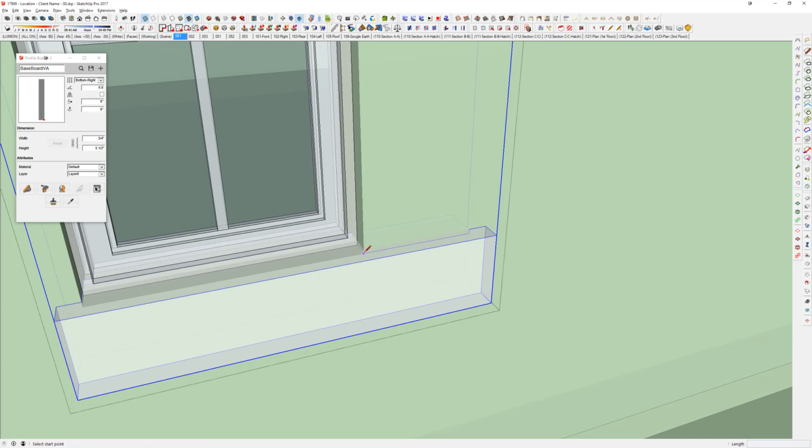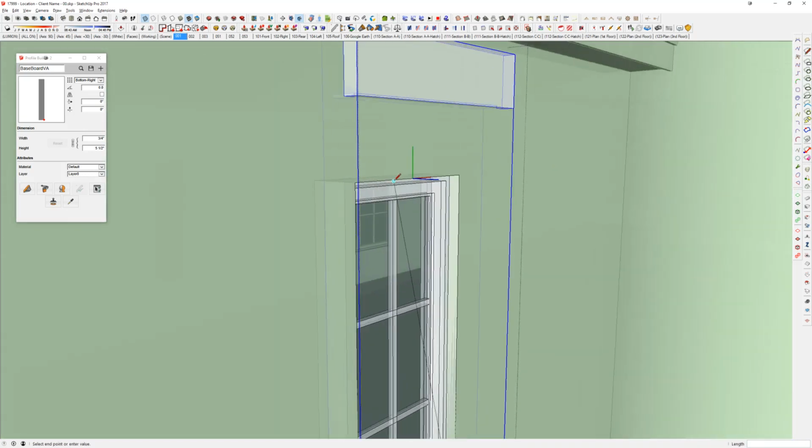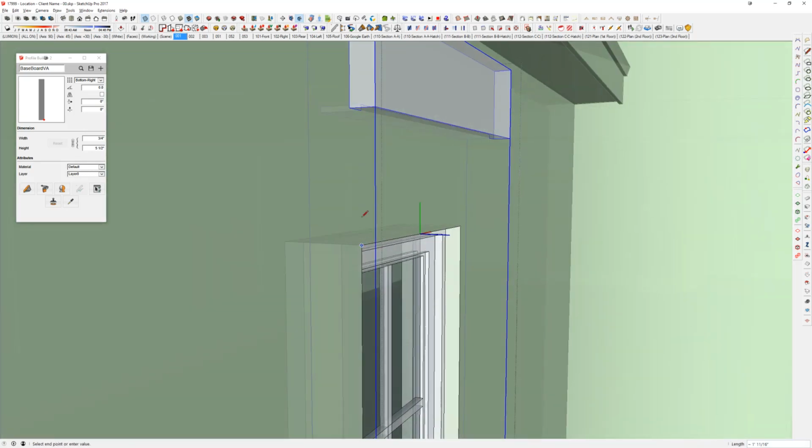And the next thing is, obviously I'm much wider than my previous one, and I can just do a quick measurement. I personally like using the line command to measure. I know there's the tape measure. I actually find that to be more cumbersome than what I need. So I use the line command and pretend like I'm going to draw a line. So I start at the point like I'm drawing a line, and I just hover over where I'm going to stop. And if you look on the bottom right, it's telling me what the length is. So it's telling me it's a foot. So I need to shrink this by a foot. And then same thing vertically. I'm going to pretend like I'm going to draw a line. And you can see that it's a foot too tall.